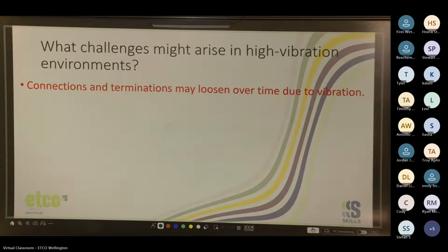Another thing you guys should know about is that copper actually heats up and then cools down and contracts over time. So when we do up our circuit breakers as tight as we possibly can, even though we've tightened them extremely well, over time they can still heat up and cool down, and the copper eventually changes shape to suit the circuit breaker.